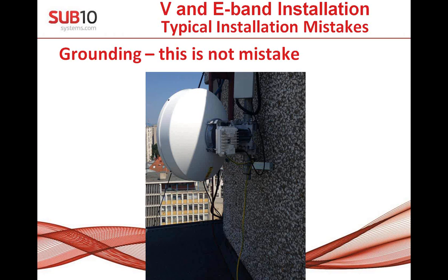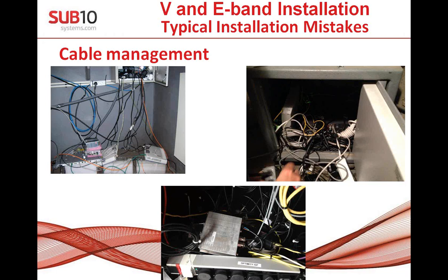Next one, its issue is the installation, which is not related to our product, but it's typical. Take care about the cable management and power supply management, because you see here a lot of stuff just on some foam on the roof, on the floor, cable going up. You see they are really short, and anybody who touches this device, which is the power supply, will definitely affect the link quality, because the link will go down.